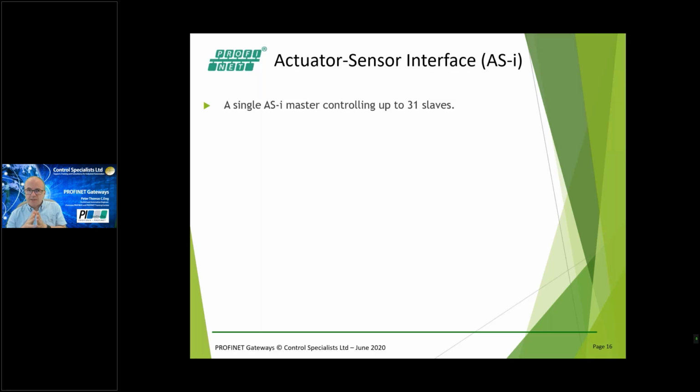It's called the Advanced Physical Layer because it's going to facilitate full duplex communication, in other words bidirectional communication, 10 megabits over the existing PA cabling. Clearly, we'll have to have an interface at the PROFINET side of things, but fundamentally it will be an Ethernet-based device.